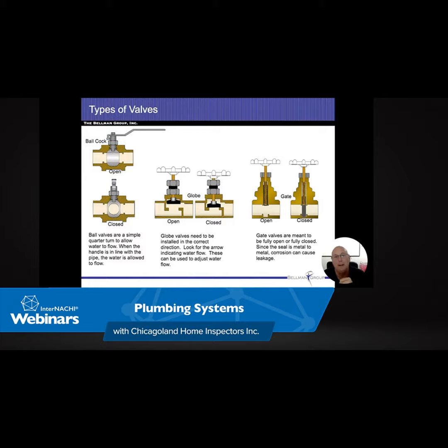These are the ones that I get aggressive on. And what I mean by aggressive is I will fill up those sinks, both of them, and I'll get them at least halfway filled up with water. Then I'm going to pull the drain on both of them and see if they drain equally, A. And then when it's done draining, to see if I start hearing gurgling sounds. If I'm hearing gurgling sounds coming out of this, then I'm not venting properly. I'm creating a siphon. That gurgling sound is siphonage that comes out of there.